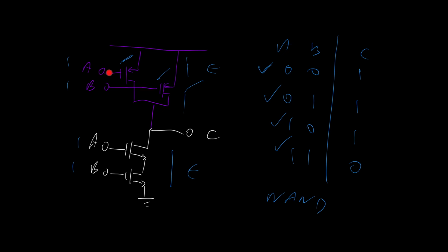And so as the voltage changes here at the transition point, for example, if this were somehow totally symmetrical, if we have a 5 volt supply rail here and we had 2.5 volts everywhere, then the resistance here is probably going to be something like 10k, 100k. It depends on many factors, but the point is, say even if we had 10k here and 10k here, we have a 20k resistor between here and here. So yes, some energy is being wasted, but it's not a short circuit as such.